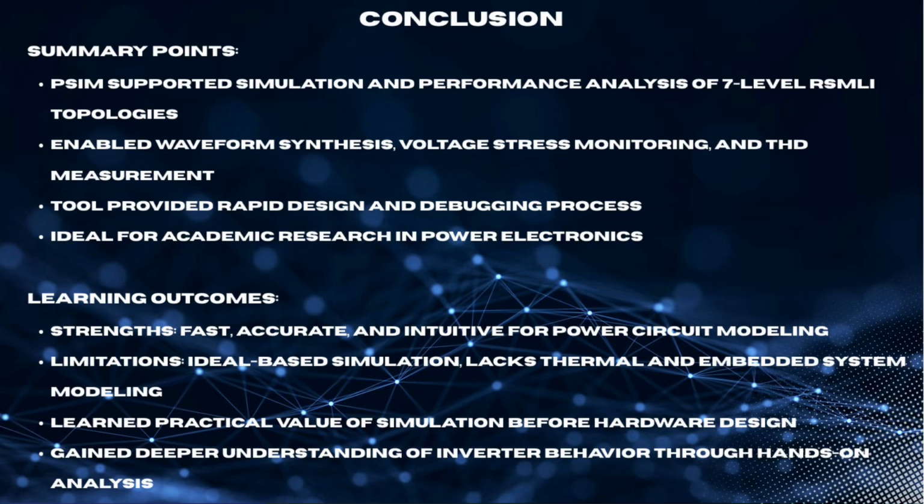In conclusion, PSIM supports the simulation and performance analysis of multiple 7-level reduced multi-level inverter topologies. It enables accurate waveform generation, voltage stress monitoring, and THD measurement, while also allowing for quick design and testing. Through the project, I learned that PSIM is fast and accurate for power circuit modeling. However, it is limited by its ideal-based simulation and lack of thermal or embedded system modeling. Overall, this project deepened my understanding of inverter behavior and the practical value of simulation before hardware implementation.